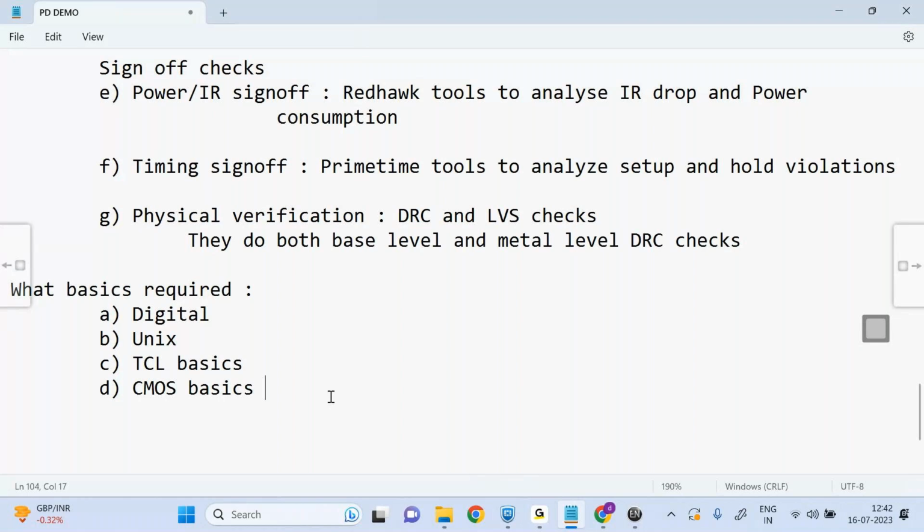What do you mean by P-type semiconductor? What do you mean by N-type semiconductor? Inside CMOS, what are all the layers present? If I take an NMOSFET, you have a P substrate, you have source and drain made up of N-type semiconductor, you have polysilicon as gate, and you have silicon dioxide in between.